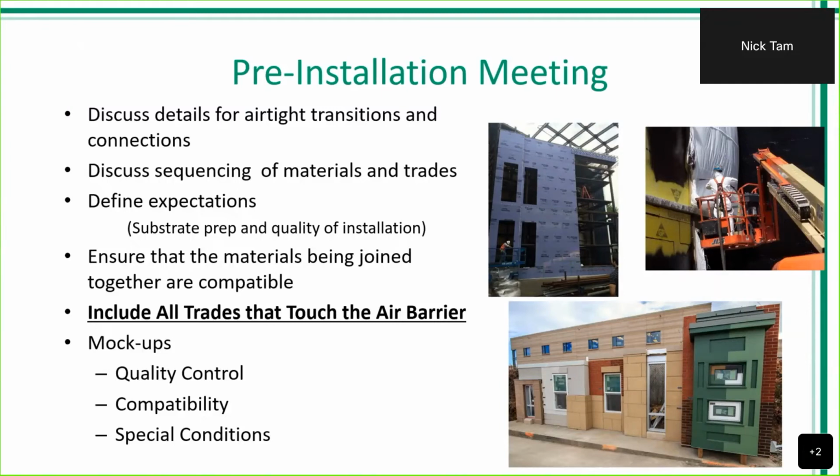When all of these can come together in a pre-installation meeting, we can discuss the proper sequencing and scheduling so that we can prevent any potential issues. Also, mock-ups are very important in these pre-installation meetings because it's not a matter of just seeing how pretty it's supposed to look. We want to make sure that we see all the segmentation. We want to know how the segmentation looks before we start it on our actual wall. This also helps us make sure that we can see where the incompatibilities may arise and come up with a solution right then and there.